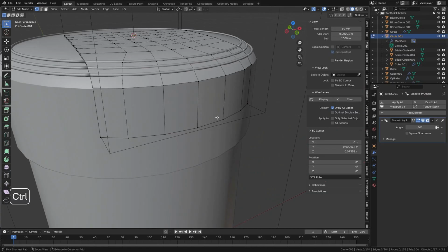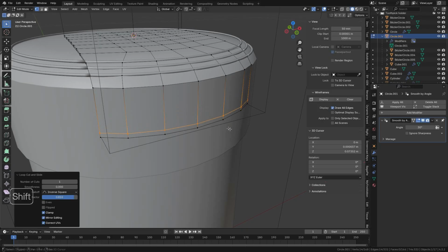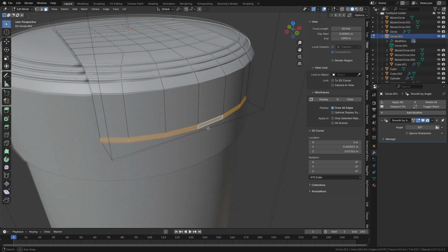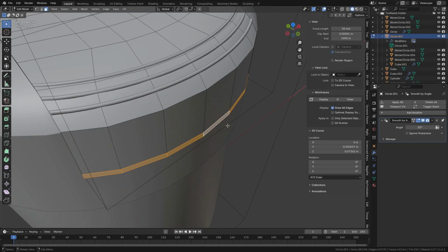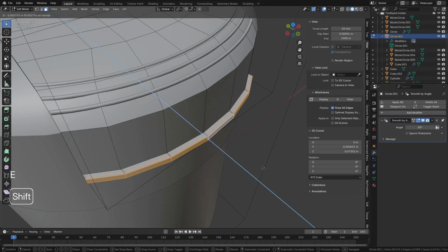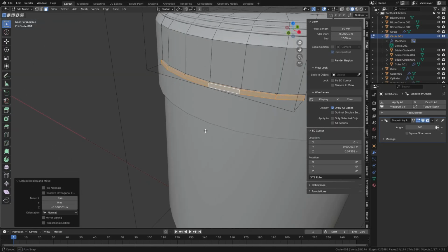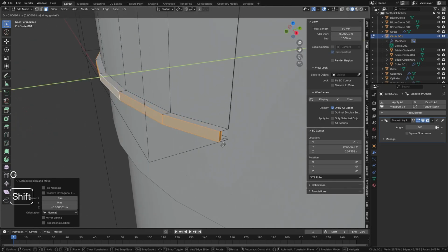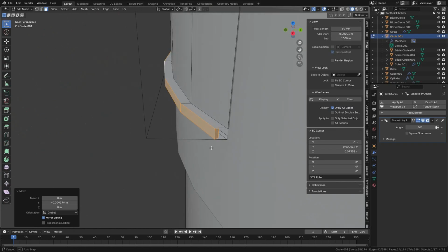Okay, so to create that hinge as I was talking about, or that little nudge or handle, we press Ctrl R, left click, bring them down here, left click again, go to face select mode, press E, make sure they are brought out just a little, just a tad. So you can bring them out here, something like this.